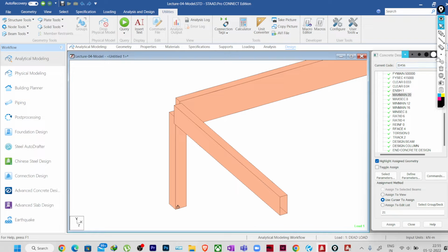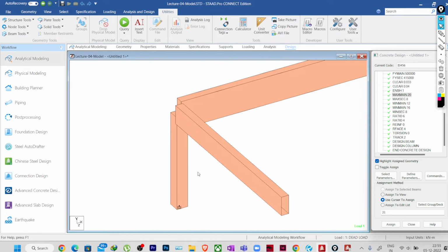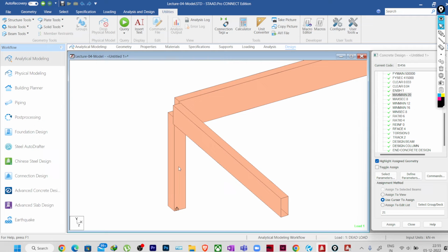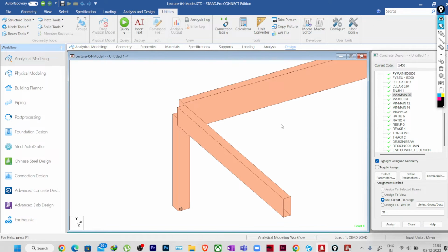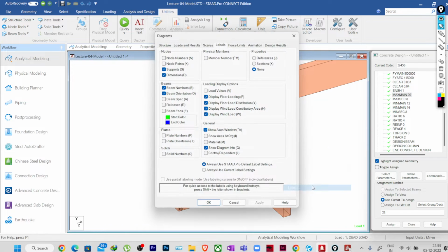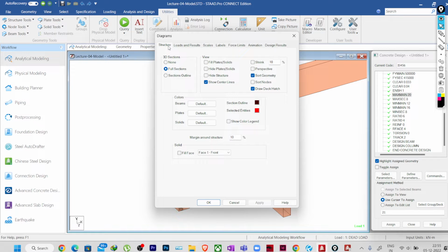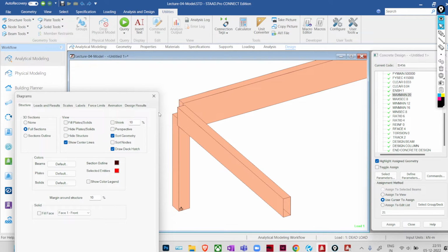So now let me also turn on the local axis. So for this, Shift O. Okay, the local axis, I think it will not be visible in case of extruded view. Let me see how we can change it. There was a command to change this view to wireframe.